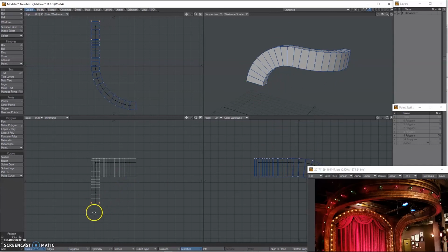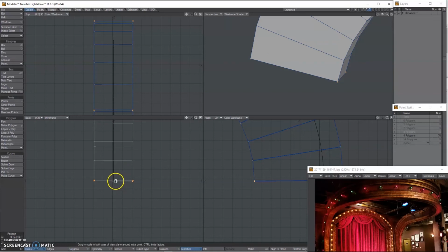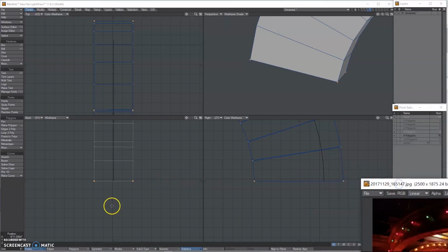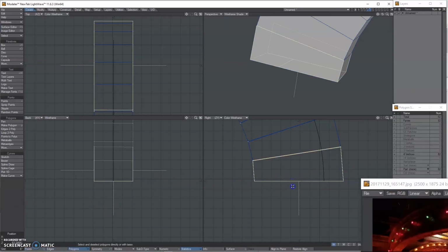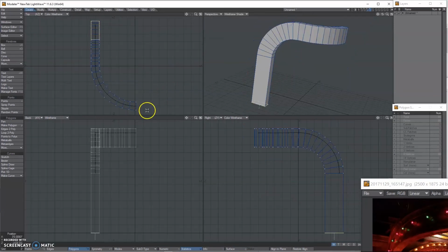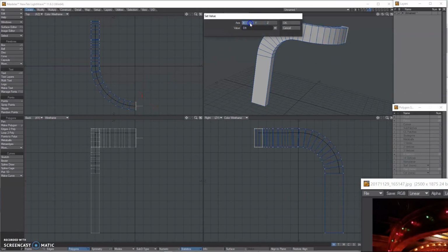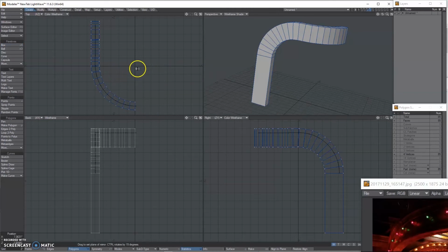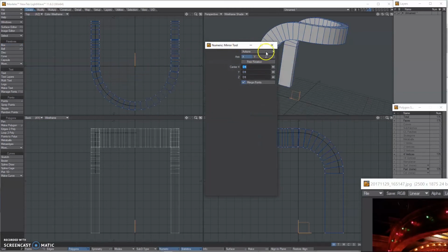And so I'm going to highlight those. Use the stretch tool H. Alright. And then I think what I'll do is I will just grab that. E for extrude, T for move, bring that down. V for set value on the y-axis 0. And that's done. And I'll set value on this to be x0. Delete that polygon. Shift V for mirrored across the x-axis.